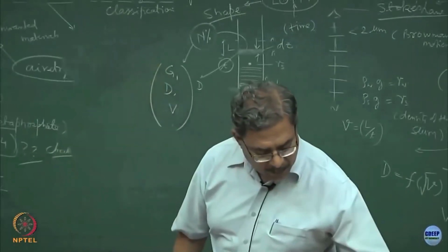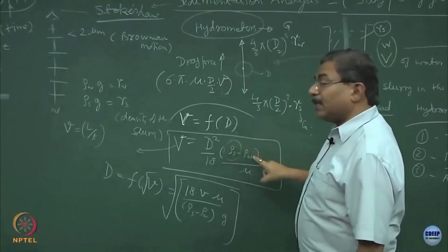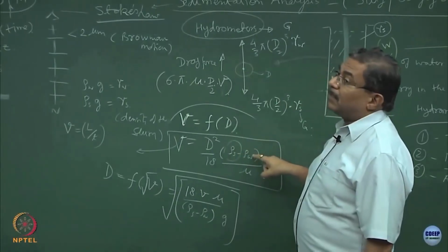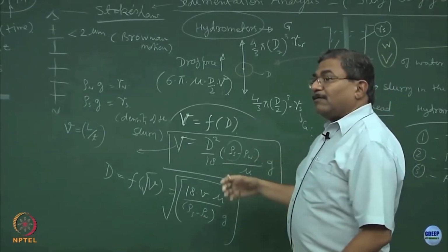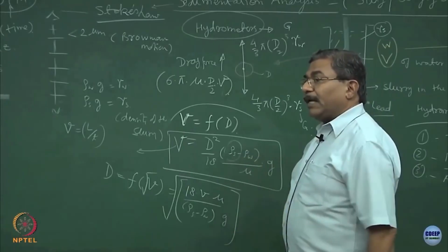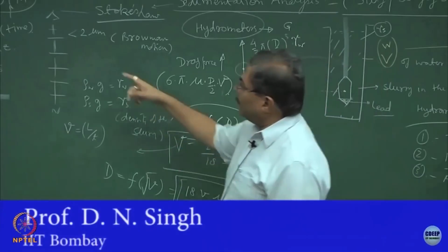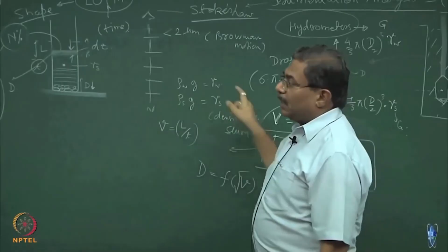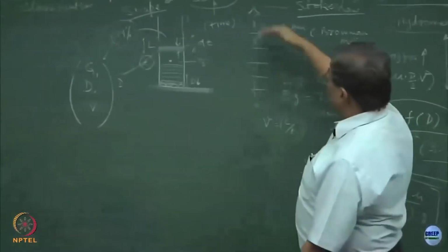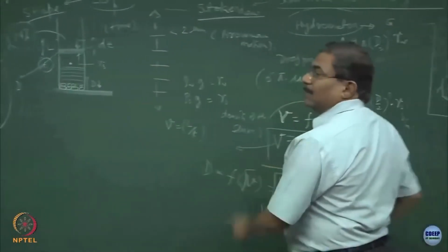Yeah, you are right, very good. So, say gamma s. If you see here, this is the density of the suspension or the slurry. So, this has to be greater than gamma w, correct, you are right, otherwise sedimentation will not occur. So, the soils which might have components lighter than water, this is another limitation he is forcing us to create now. In this series, if the soils are organic in nature, they cannot be used, and hence you get rid of them, because they will be floating only on the water surface and they will not settle, and hence this analysis cannot be done. This is another limitation.